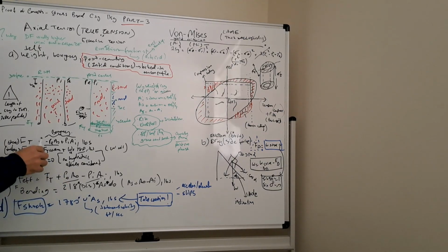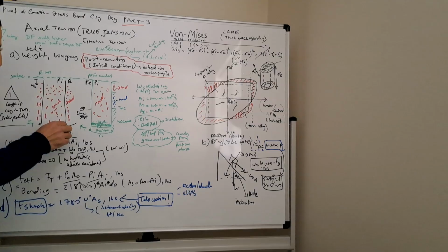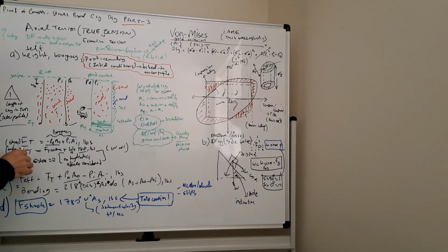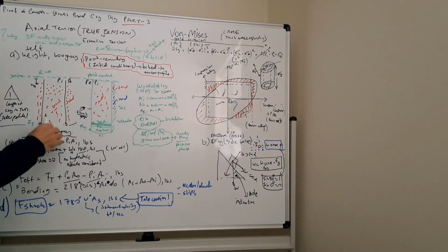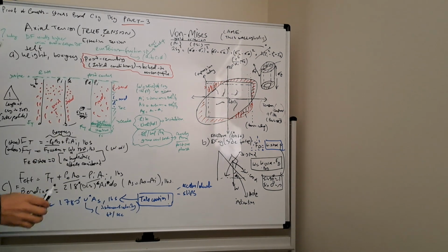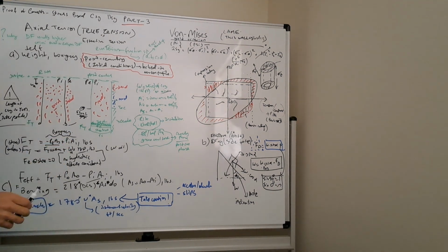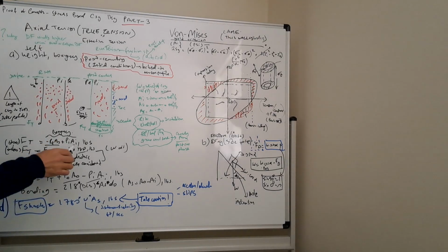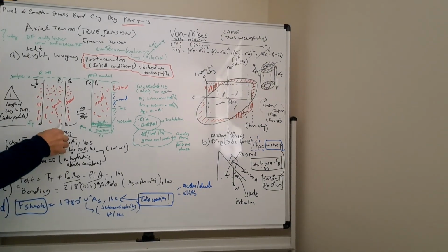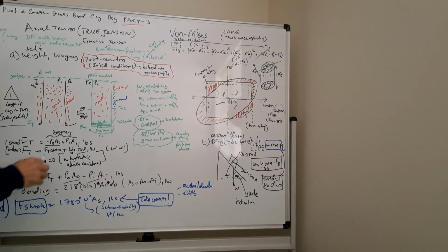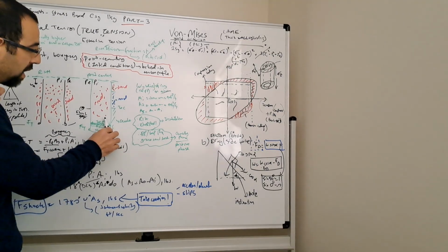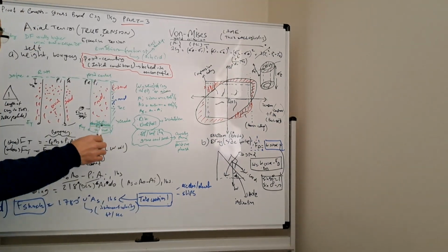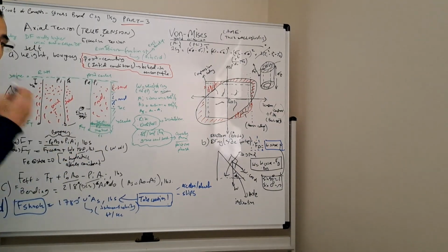So what we can draw from here is, at the shoe area, your true tension is negative almost all the time when your external pressure is higher. Of course, in the running hole case, it will be still higher, so that your true tension at the shoe is negative. However, your hydrostatics are similar. So how minus it is will be due to the difference of the outside area or the inner area. However, in the cemented case, because you have the cement on the outside, the hydrostatic difference is also higher.